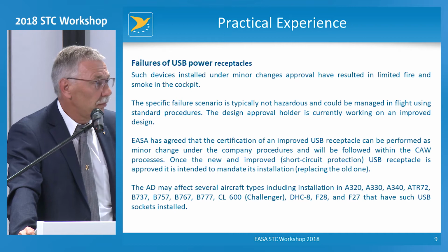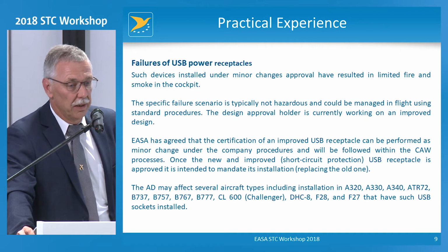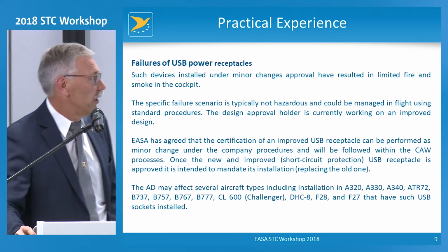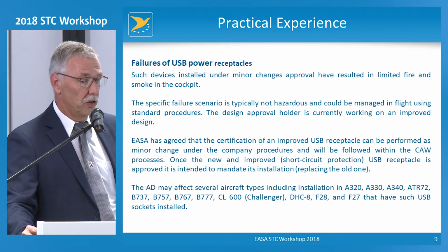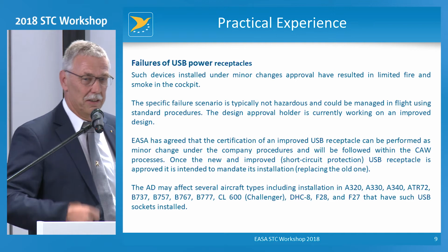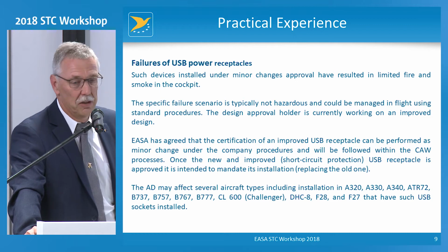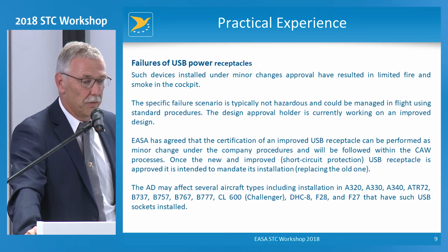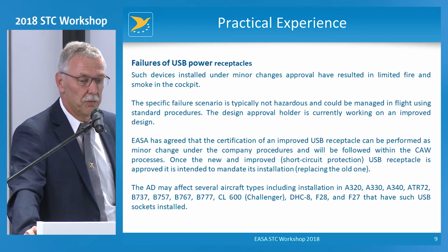What we have here is a very small thing, but it's on several airplanes. USB receptacles have become very common in the cockpit area, and can be designed under a minor change because they typically should not have a lot of impact on continued airworthiness. But here it has been observed that they start smoking and burning, and the specific failure scenario is not so critical. It's not hazardous and can be managed by flight procedures, but it's certainly not good.